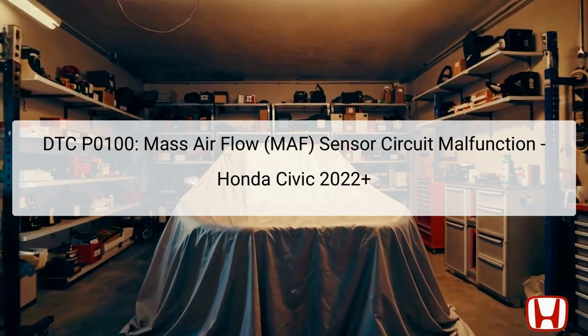When there's a failure in this circuit, the PCM identifies the issue via lower than expected output frequency from the sensor. Consequently, it stores DTC P0100, alerting the technician to investigate this component along with related circuits.